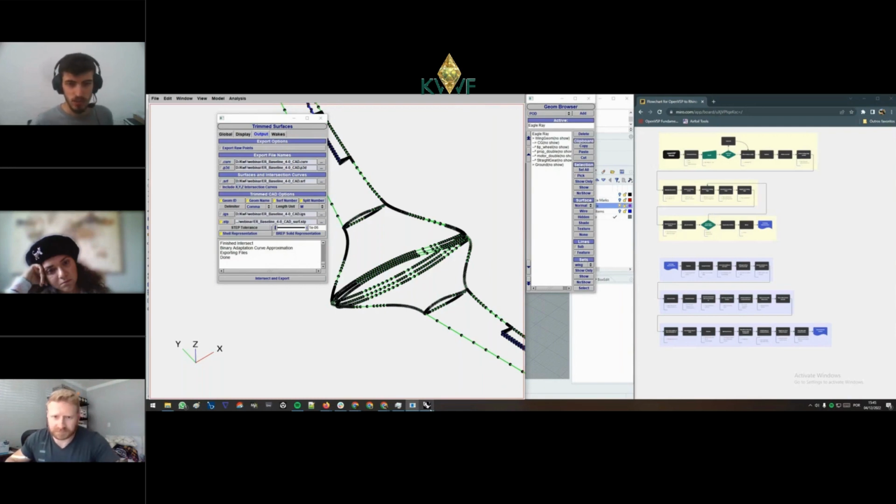We actually didn't try to change the step tolerance on OpenVSP, but that's a very good idea. We did change the tessellation of the wing surface in OpenVSP just to see if it responded better in Rhino. But even with the small tolerance on the OpenVSP model, with the rebuild command that we used, we were able to clean up all these excess points and still have a perfect surface. But that's a very good idea to try to eliminate a step in Rhino.